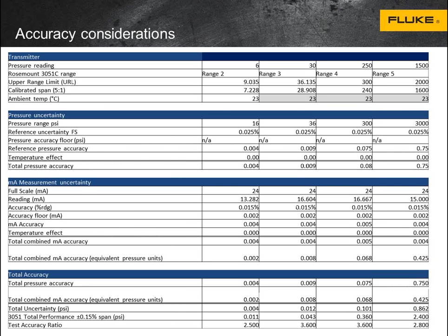So this eye chart, this large graph, is actually what's called a TAR. We talked a little bit before about TURs, which look at all the various types of uncertainty. A TAR, test accuracy ratio, really only compares the unit under test and the calibrator. Both of those things are specified by their respective manufacturers, and you can calculate a TAR quite easily without really thinking a great deal about the field conditions.